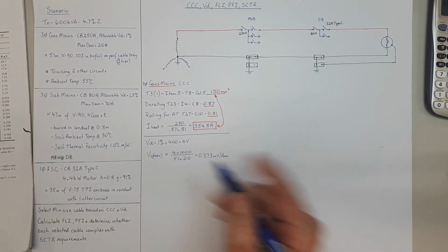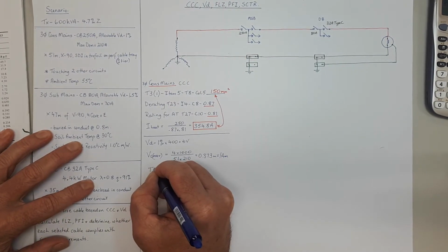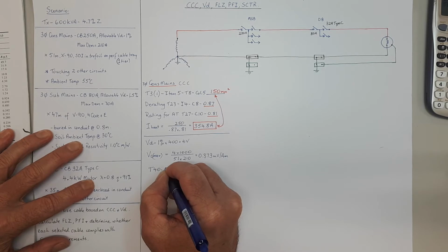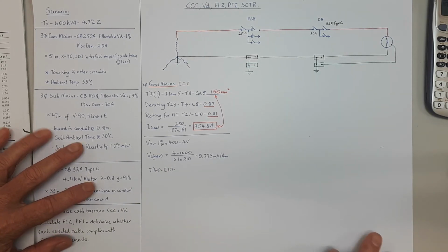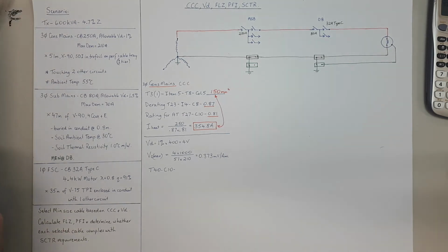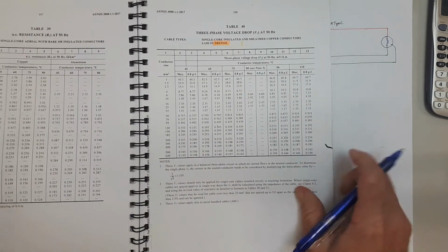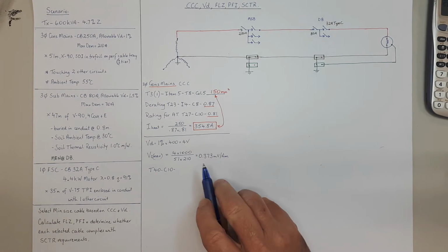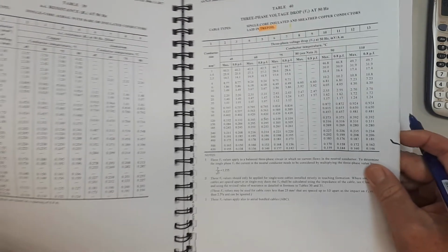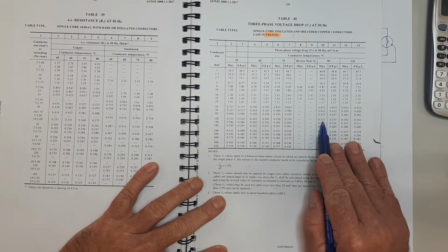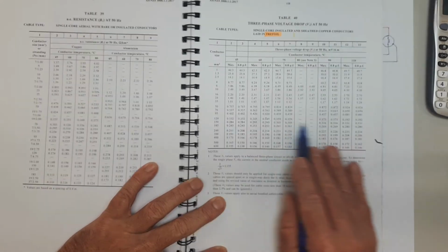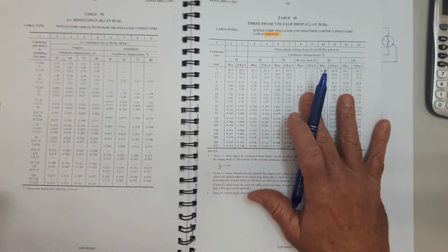So we write in our table reference, table 40, column 10, and we scroll down. We scroll down there, table 40, column 10, here we are. We're looking for a maximum of 373. It can't be any bigger than that. So down, oh, we're right on, 373 there. We could get away with 120 mil.